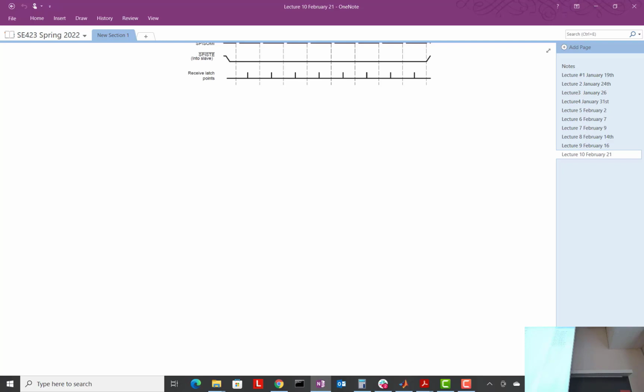We get interference on there, and that always messes things up. That's why, with old TVs, and it's still true for today's TVs too, we can still get noise and see garbled pictures. But if you keep the analog part in a little chip, the amount of interference is usually a lot less than if you send that analog signal over long wires. So a lot of things do the little sensing right on board the chip and then send the data to you digitally.